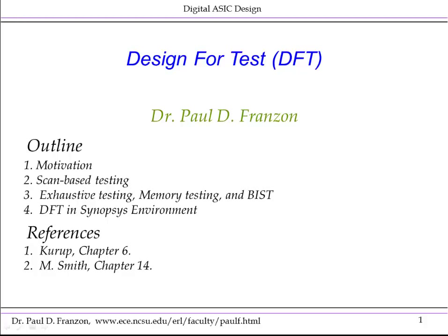Hello and welcome back. The next module we're going to look at is design for test. What you'll see in this module is that features will have to be added to the chip to help in manufacturing test. Typically the designer is involved in adding those features, and a designer who is aware that these features need to be added and is involved in actually adding them will end up with better designs.